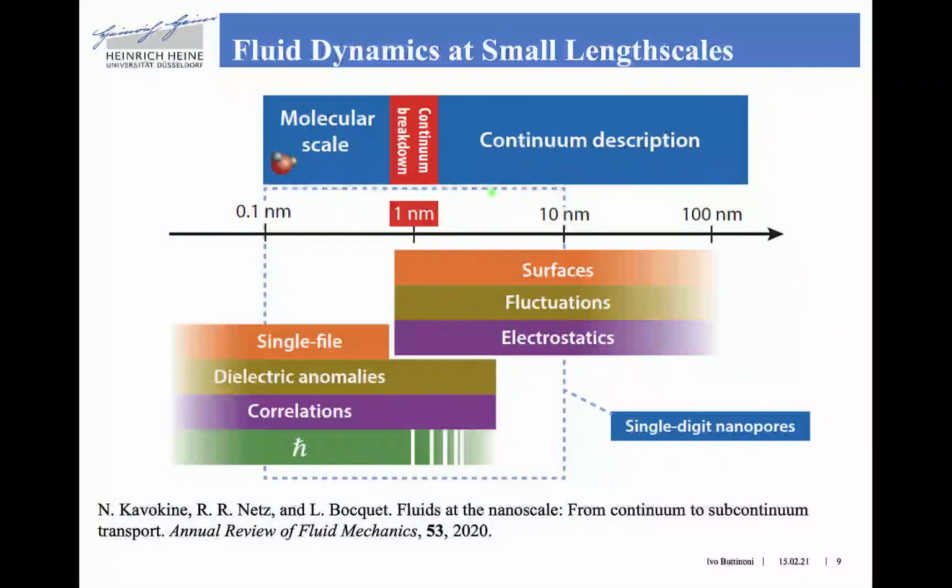In fact, even though a continuum fluid dynamic description based on the Navier-Stokes equation is valid above 1 nanometer, which is the lower limit for which one can define the fluid viscosity, all the interfacial phenomena which occur near the solid surface, as for example near the channel's wall, are very important in the sub-micrometer range, and lead to non-negligible slip velocities.